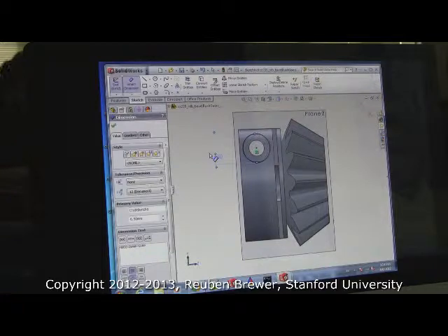Yeah, so sometimes the snap to things are really finicky, especially with the level of zoom. If you're too zoomed out or too zoomed in, or even if you're too slow, like if you were to just drag your mouse really slowly, it won't do it. So if it's not working, try changing your zoom, doing it a little faster. Unfortunately, it's an art, not a science with the snap to. Is it snapping to? You can click on the circle maybe.